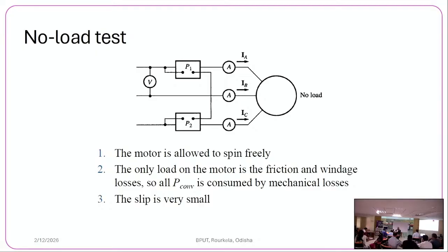Think and tell, let us have an AC resistance. Now the inductive reactance will be more, so the resistance part will be less. Current will move in the outer side more. Exactly, this is the correct point. That is what I want everyone should know.